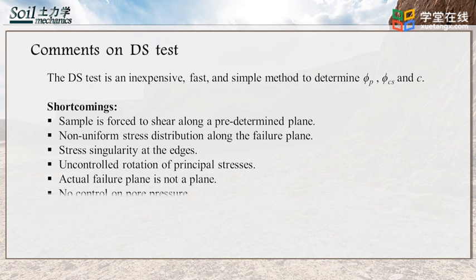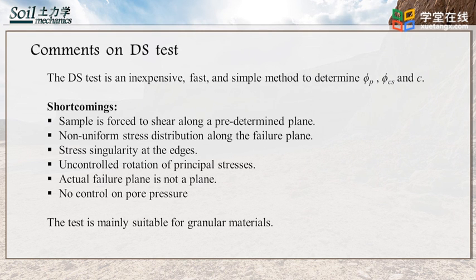Stress distribution along the failure plane is non-uniform, and there are stress singularities at the edges. The rotation of principal stresses cannot be controlled. The actual failure plane is not a plane. One cannot control the excess pore water pressure.